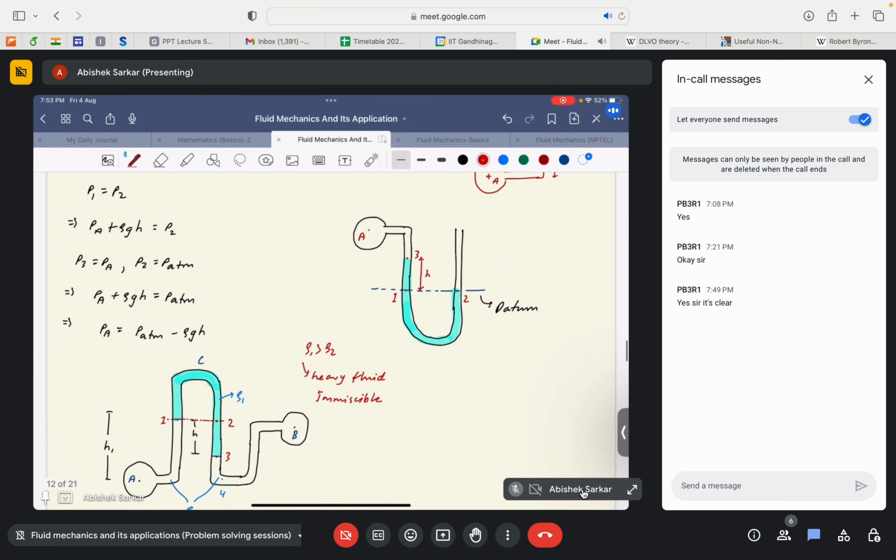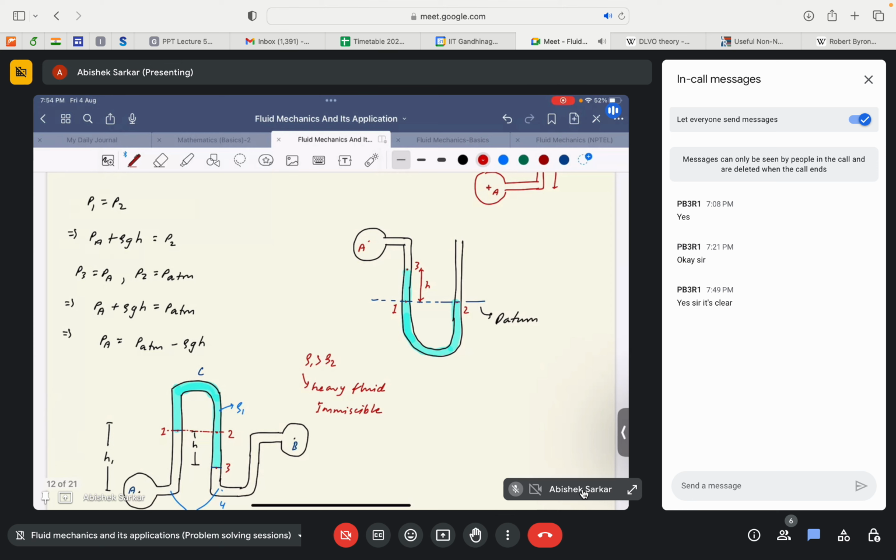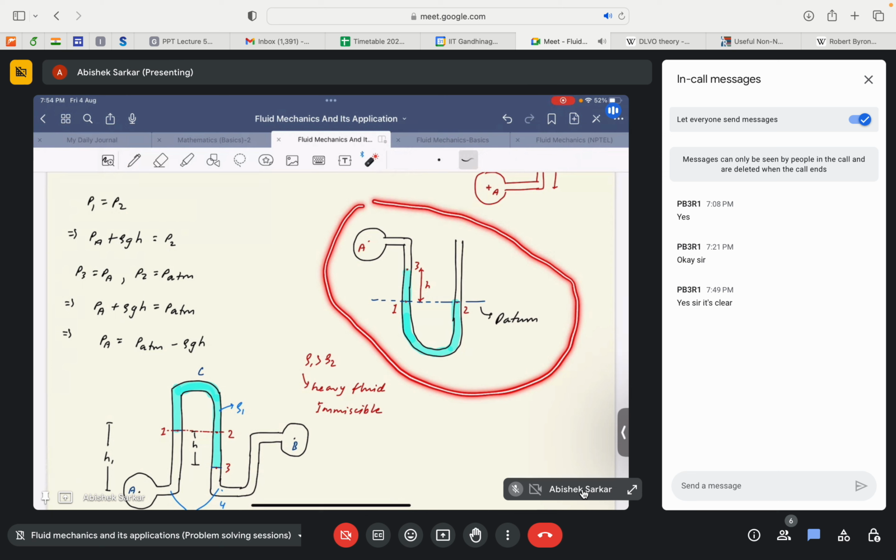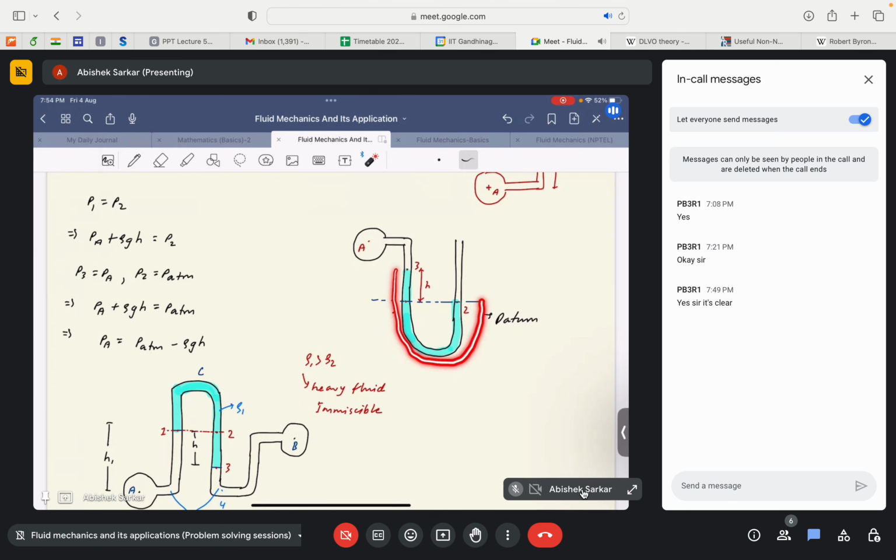Okay, so it is a very simple trick, by the way, in which pressure can be calculated with the help of a manometer, right? So I will just tell you with the help of this example. Similar example was also taken by Professor Gupta in his lecture, just to reiterate so that the concept is clear. So if this blue fluid in the manometer denotes the manometric fluid that is being used to obtain the pressure in the duct A, so if this is the diagram that is being given to you, we basically take the lower end of the lower interface as our datum.